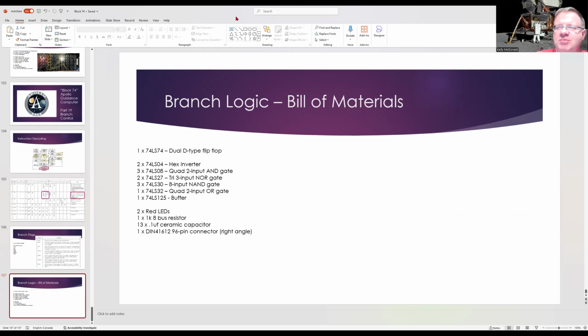And that starts getting a bit complicated because we not only need to decode the contents of the sequence register in order to generate instructions, but we need to combine that with branch. And there's a few other flags that are part of the process that are used in order for us to generate the appropriate instruction, things like the extend bit and a few others. So it'll probably be a couple episodes for us to work through instruction sequencing and the sequence register.